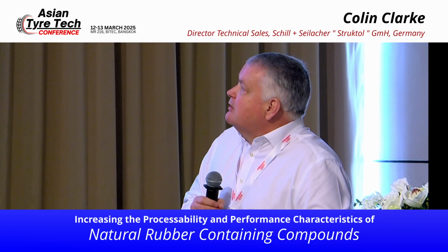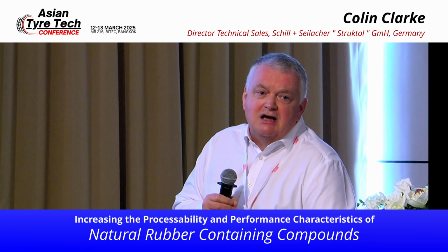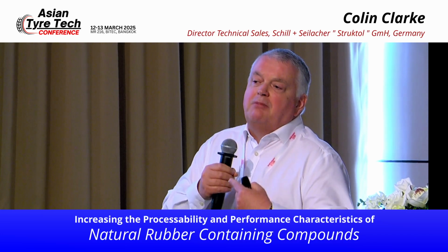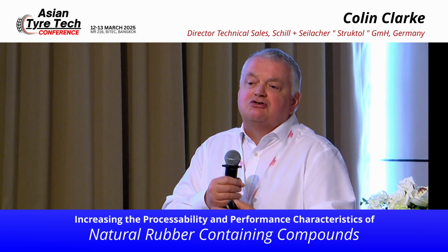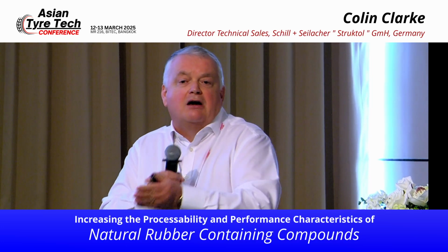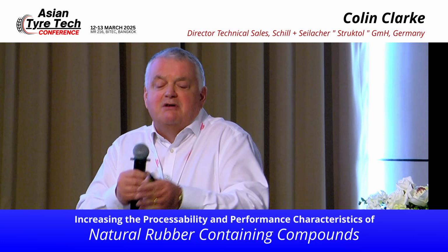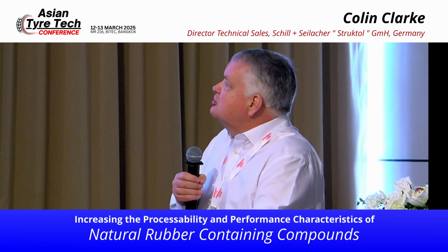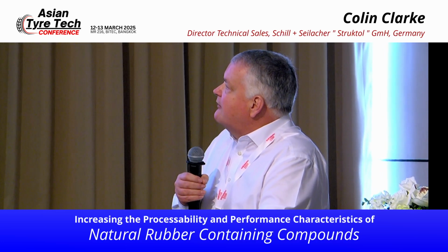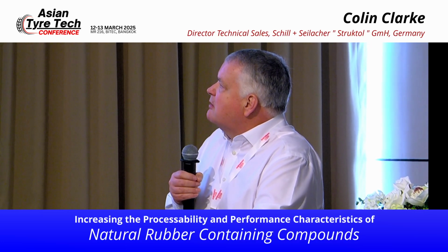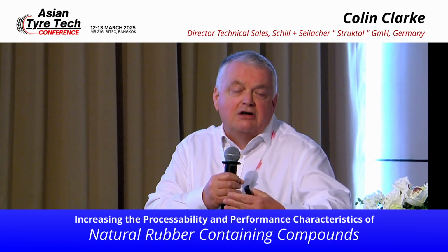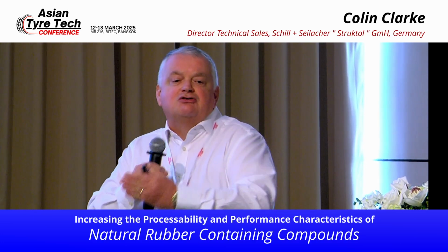Effectively, with chemical peptizers, we can do that, but we're very limited. Chemical peptizers should not attack the synthetic polymer. The chemical peptizer is, in a way, deactivated when we add carbon black. So we're quite limited in this so-called in situ mixing, same stage, in that we have to complete it in the very, very early part of the mixing, because when we add carbon black and the other ingredients, we lose the peptizer efficiency.